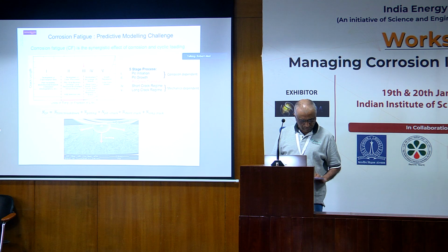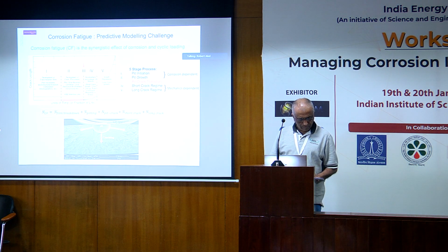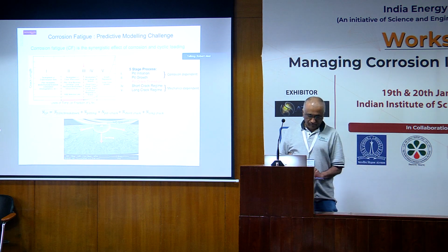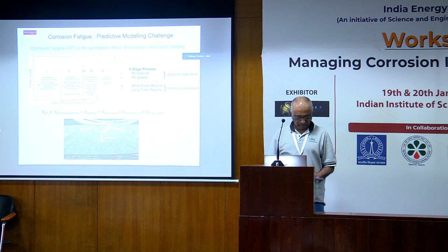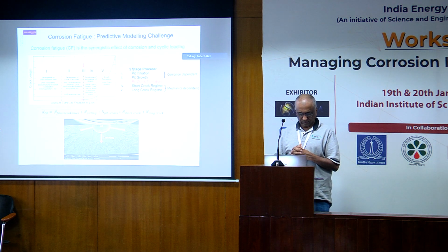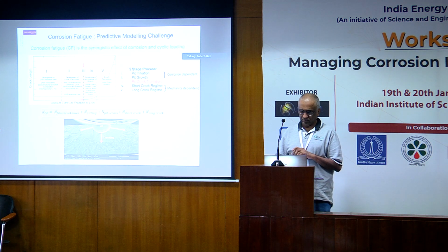If you increase the surface oxide film, you delay the onset of the intergranular corrosion. This is, I guess, the benefit of modelling, that you can play around with the parameters of the model to try and affect what we might be seeing in a real service environment.